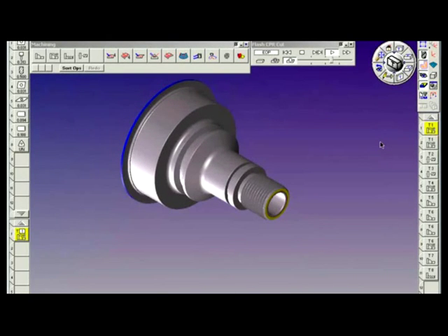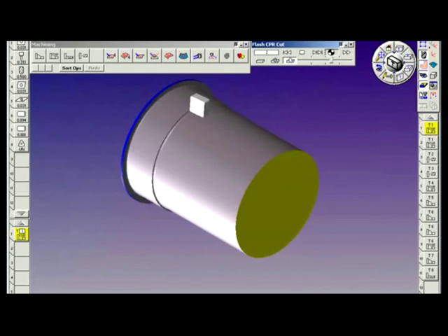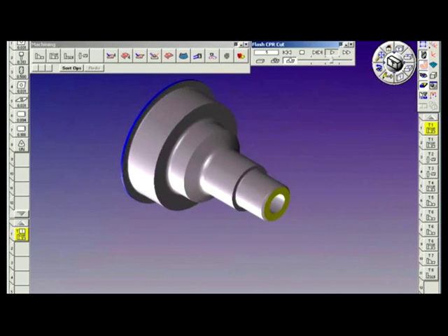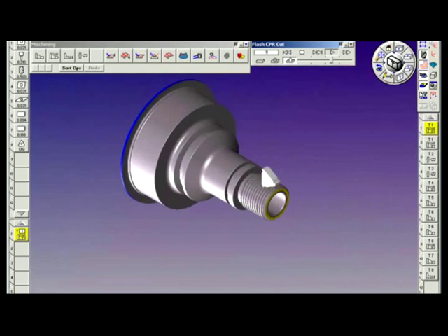This class is a production lathe class. We will be generating toolpath for this particular part that you see on screen. We will take a series of predefined tools, do facing, turning, grooving, threading, and some ID operations on this particular part. I'm sure all of you have seen it at some point.